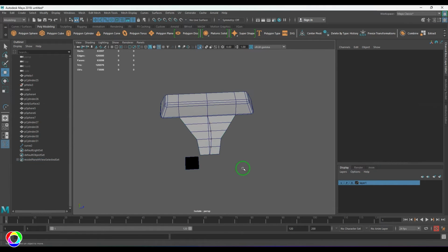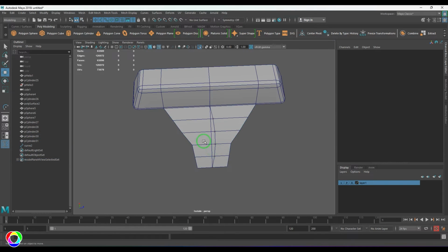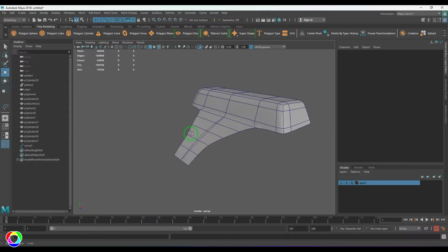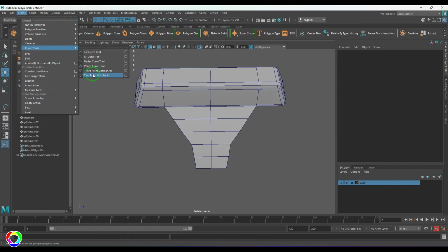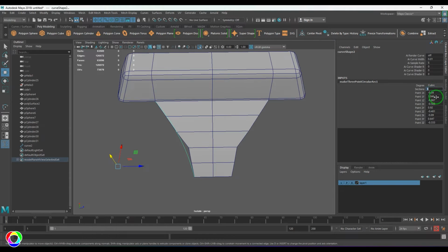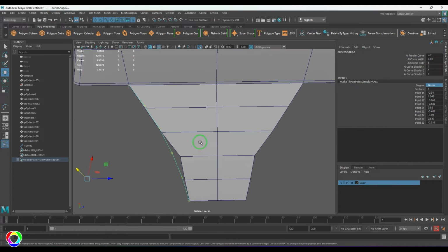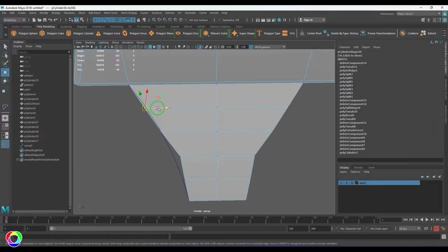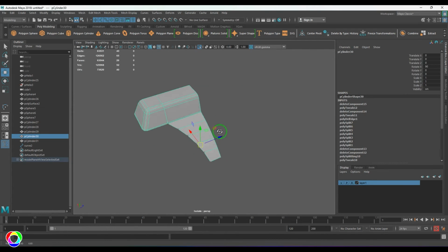I can also, okay, let me first see whether I got the arc. Yeah, that looks good. I'll be taking a very similar technique here, which is going to be a 3-point arc this time. So I'll put one here, one there, one there. Okay, then access to 5 linear, display, nurbs, edit points, and then snap it there. Okay, I think I can delete those faces.